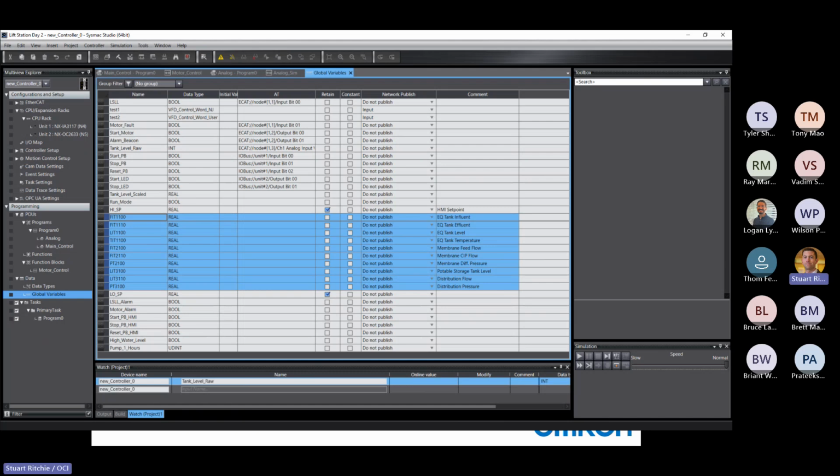This is handy when you've got engineering documents like tag lists that you want to follow or a shutdown key, something like that. You can even use some of the tools in Excel to aid with tag naming when you have a lot of similar tag names with prefixes or suffixes. There's some tools in Excel you can use to even generate tags for you. You can take advantage of those. So did everybody get their tags to paste back into Sysmac properly?